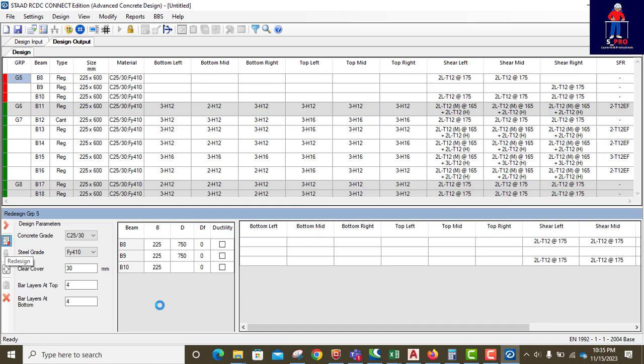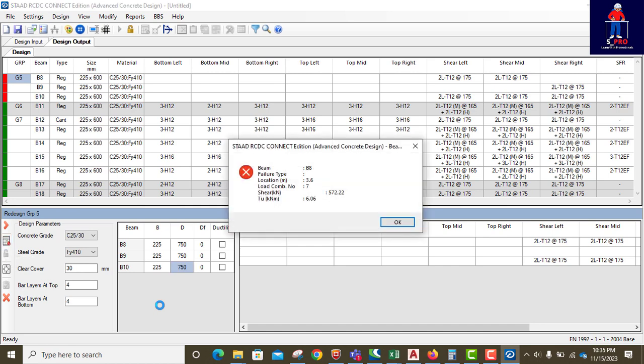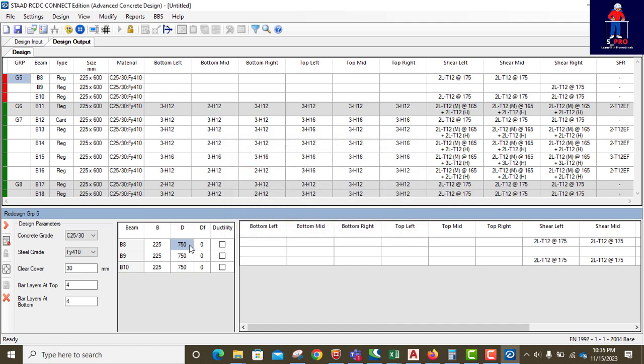If that happens again, we'll just take it to what the other one accepted, 1 meter depth. See, that's the same thing. So we just do 1 meter depth, or 2. So these two beams will be our special beams in this structure. So we are going to pay special attention to them, or we go and introduce more columns under those structures.